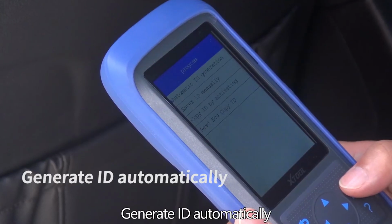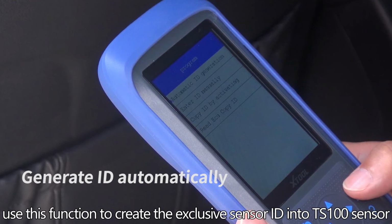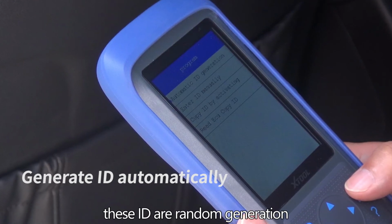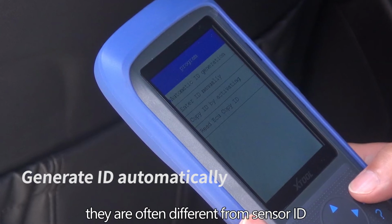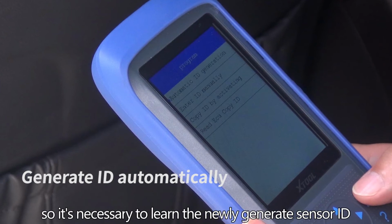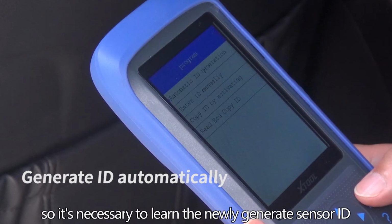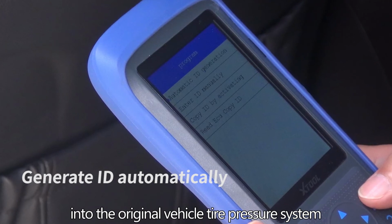Generate ID automatically. Use this function to create an exclusive sensor ID in the TS100 sensor. These IDs are randomly generated. They are often different from the sensor ID which is stored by the original vehicle tire pressure system. So it is necessary to learn the newly generated sensor ID into the original vehicle tire pressure system.